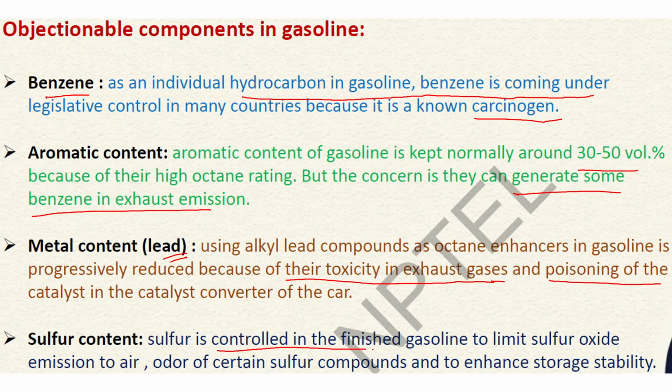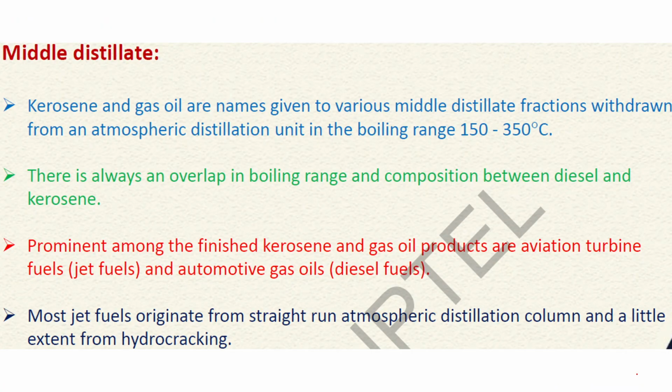the gasoline, then in the flue gases there will be a large amount of harmful gases such as sulfur dioxide, which may be emitted into the air. Moreover, the odor of certain sulfur compounds is very obnoxious, and sulfur also affects storage stability. So we need to minimize the sulfur content in the gasoline as much as possible.